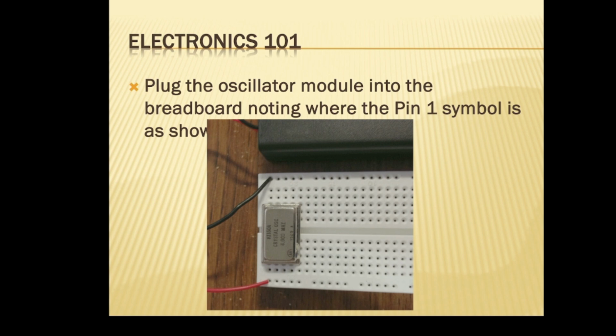I need to look at pin one, where's pin one? Because I don't remember. Here's the working one. All right, we got it right here. Pin 14, so we go 1 through 7, 8, 9 through 14, so pin 14 goes to plus rail power, that's good. Pin 7, which will be the bottom one right there, goes to ground, that's correct. And the output is on pin 8, which is the top one right there. So that's our output and that's our ground, that should work.